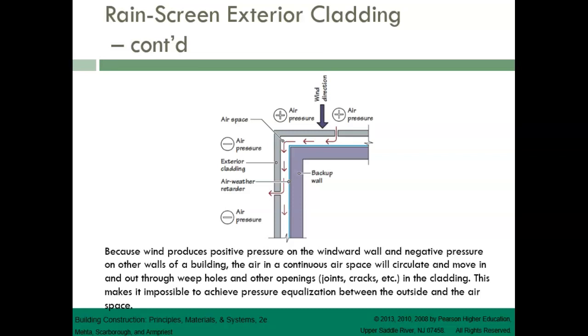Water will also be sucked into the airspace through joints in cladding that are inadequately sealed or have become leaky over time. Water suction will take place on the windward facade only, because at this facade the pressure in the airspace is lower than the outside pressure. On the other facades, the airspace pressure is higher than the outside pressure, hence no suction takes place through non-windward facades.